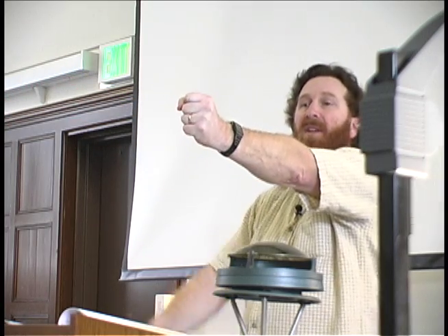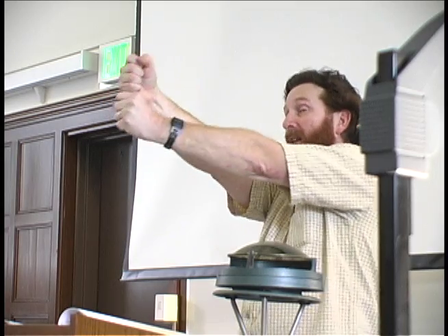So to make it a little easier, if you want to do a site assessment, go out to where you think you want your panels, face true south, 18 degrees east of magnetic south. So if you're facing magnetic south, just shift yourself 18 degrees to your left, and that's true south. And then hold out your arms like you're going to give somebody a big hug. That's 9 o'clock, that's 3 o'clock. And then put one fist in front of you, the other fist on top, and that's 20 degrees.